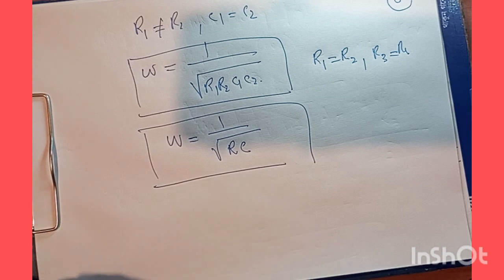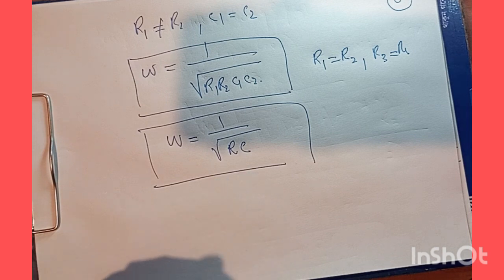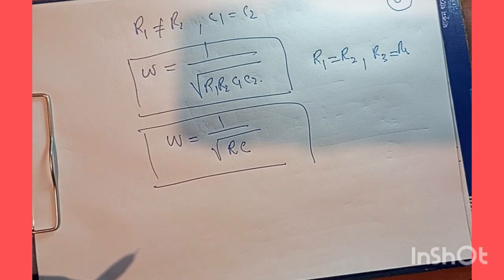And after that, we went for the equivalent circuit of the circuit that we had originally drawn, and then we made certain approximations, and finally we evaluated some of the equations, and we were able to calculate the angular frequency, the resonance frequency for this oscillator.